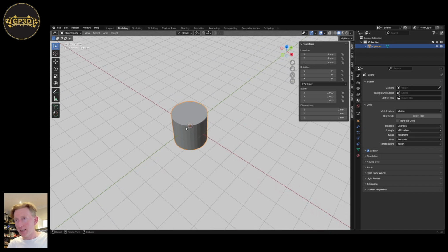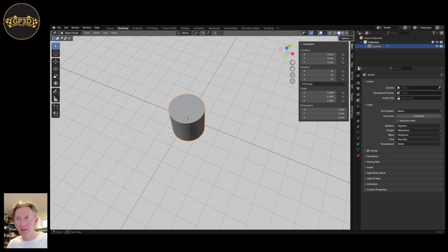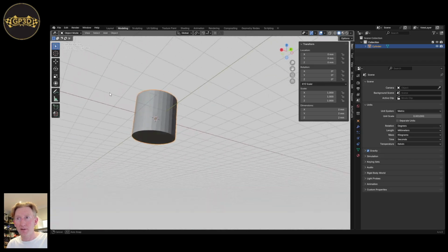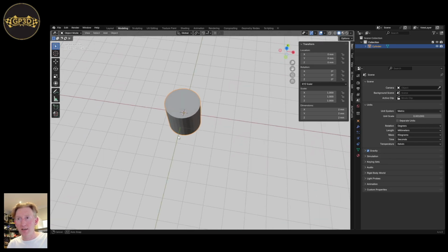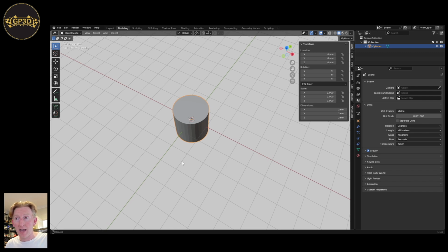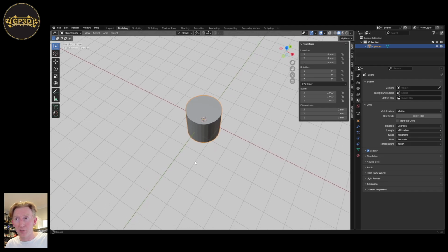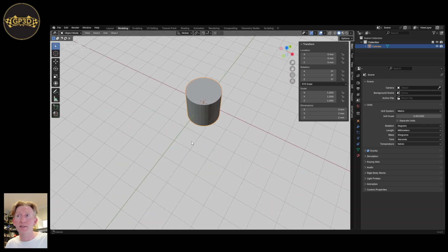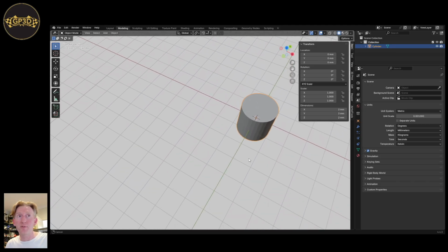Okay, so a little bit of navigation again. Remember, hold down the scroll wheel and move the mouse, and you can move around the 3D space. You can move around the object. If I want to move its position, I hold down Shift and press the scroll wheel down. So click the scroll wheel and hold it down and move the mouse. So that moves it in this way.